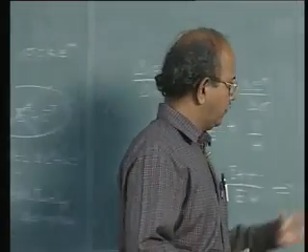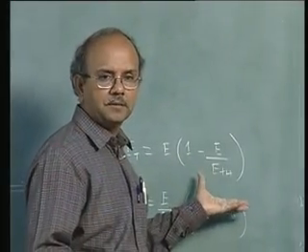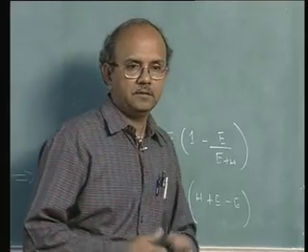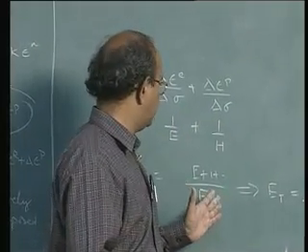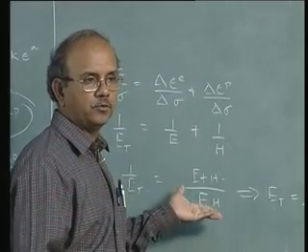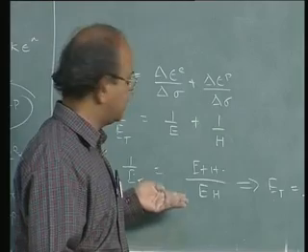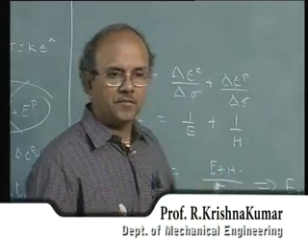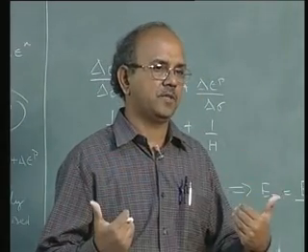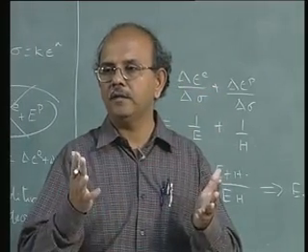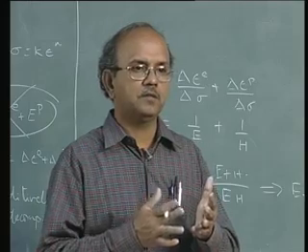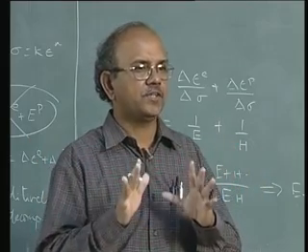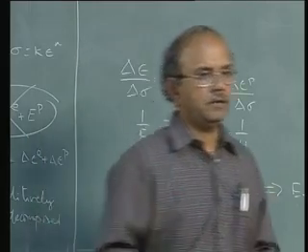So we will continue with this in the next class and see how to use Et in order to write down KT, the stiffness matrix. You can retain EH by E plus H itself, it doesn't matter. Anyway, I need only the Et. So the lesson is that Et is derived from E and H. Even if H is not given, it does not matter in a problem. Et is just d sigma by d epsilon. If it's expressed as k into epsilon power n, you can write d sigma by d epsilon to be n k epsilon power n minus 1 and so on. So Et is just a function of the strain as well. We'll see in the next class.